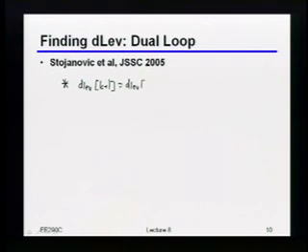Again, as usual, since I want to drive the error to 0, I'm going to build this as an integrator, which in discrete time just means an accumulator. So in other words, just like before, anytime I notice that my error is positive, I'm going to move my reference up. If my error is negative, I'm going to move my reference down.